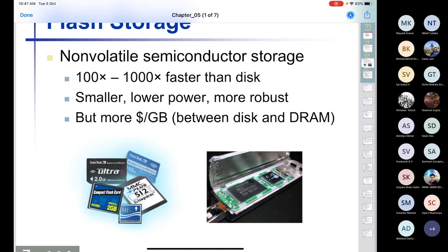However, flash memory works in a different way, by forcefully pushing in current by creating large electric fields across the oxide layer, and stores values inside the devices that way. They have extremely large integration density. Their speeds are slower than SRAM, but almost approaching. And they have much lower energy consumption than SRAM or even DRAM.